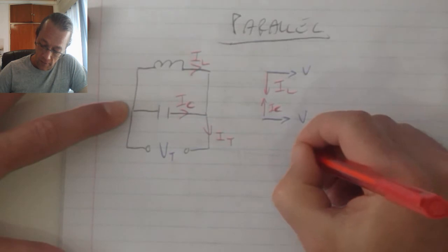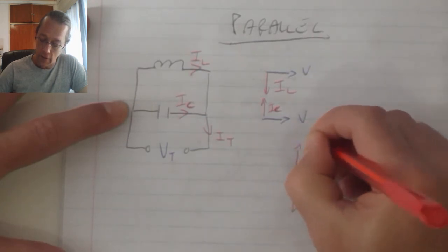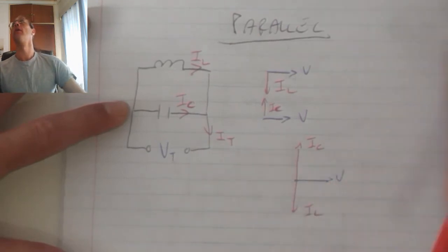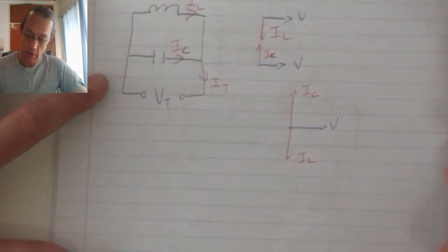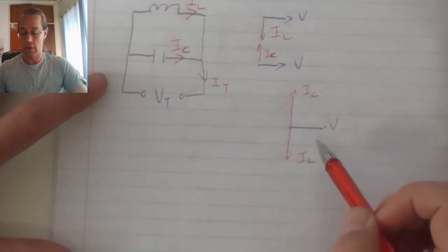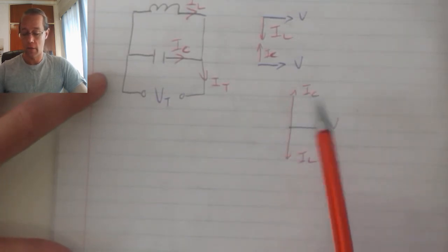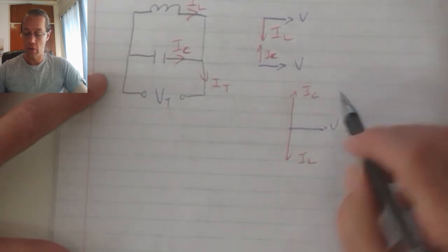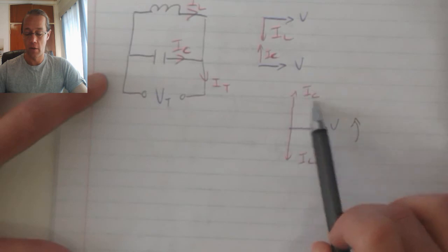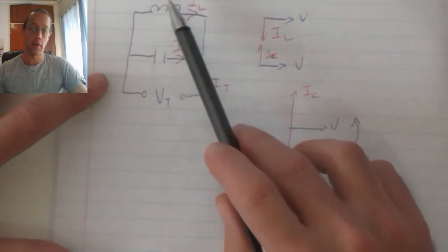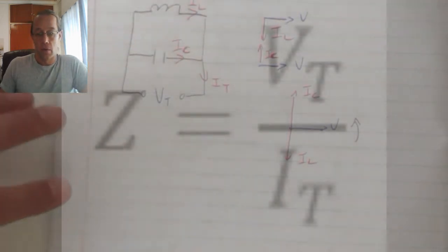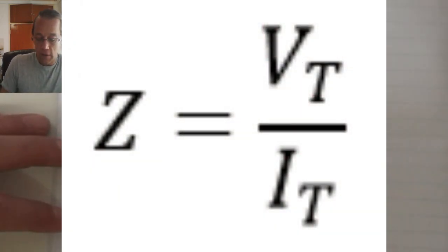we're going to find again that they are in opposition to each other, IC versus IL, inductor current versus capacitor current, and that in effect is going to cause, as we get the rotation, the current to transfer from the capacitor to the inductor and then from the inductor to the capacitor, depending on where we are.